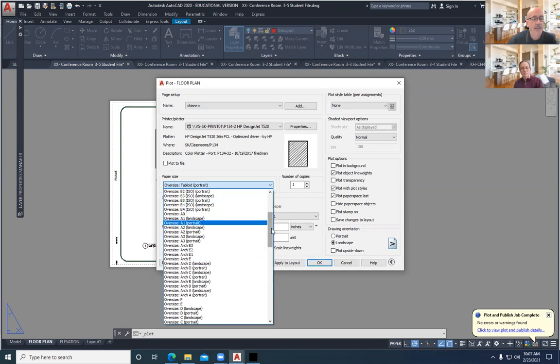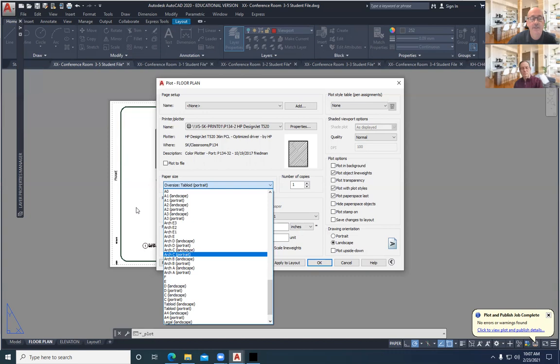And so that's the other thing that you can do with your drawings is that scale is determined by how much area you have to print in. If I'm printing on an 11 by 17 sheet of paper, then my conference rooms need to be scaled at 1/8 of an inch equals a foot. But if I have a bigger sheet of paper, I can scale them bigger.